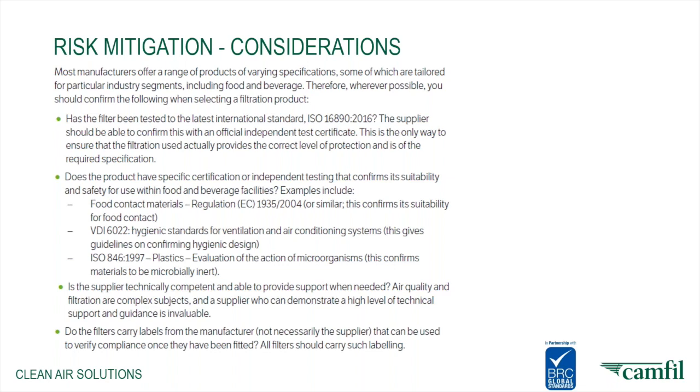Do the filters carry labels from the manufacturer, not necessarily the supplier, that can be used to verify compliance once they have been fitted? All filters should carry such labeling. As I've said in the previous slide, especially with the Eurovent certification and labeling, all filters being supplied to site must carry the manufacturer's label, not the supplier's. This is the only way to clarify what filters are in use and if they are compliant. This allows us to check independently the certification on the Eurovent website as well.